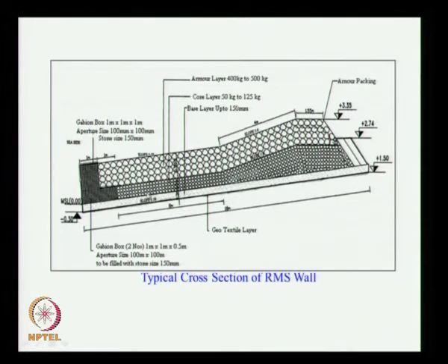With a slope of 1:10 and 18 meters, the vertical elevation difference will be 18 divided by 10, that is 1.8 meters. So here we have minus 0.3 meter, which means here you will have plus 1.5 meters, right.